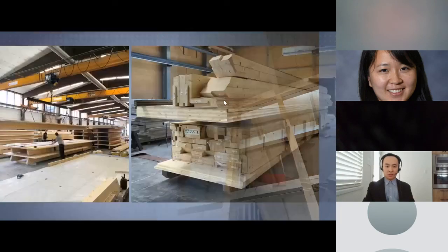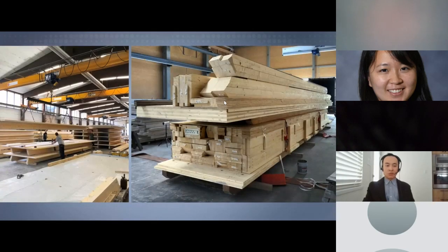And here you can see on the left is a picture of the ribbed roof panel supported on load-bearing stud walls on the perimeter. On the right, you have ribbed roof panels supported on glulam posts and beams, which are going to be infilled subsequently with glazing. And these are some of the prefab components, including ribbed panels and glulam beams.